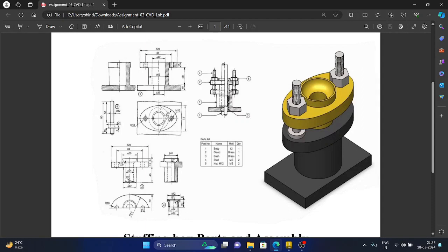It should be greater than the maximum of the given dimension. So the given dimension is 72, it should be greater than this. And same thing over here, this is 120, it should be greater than this. The free size has to be greater than this. So we are going to select 80 cross 140, let's say, not 80, 90 cross 140.